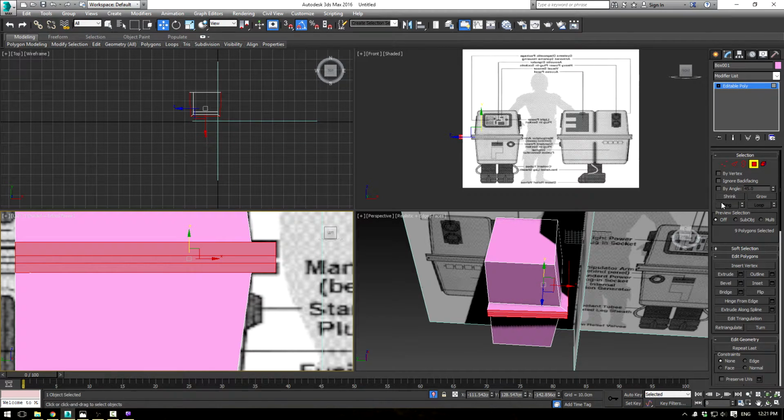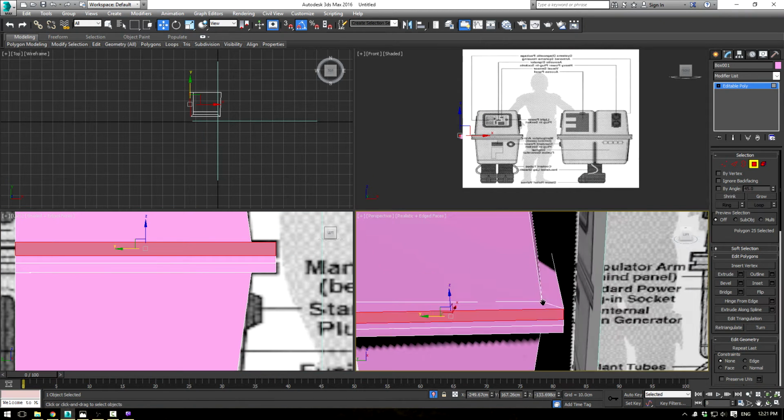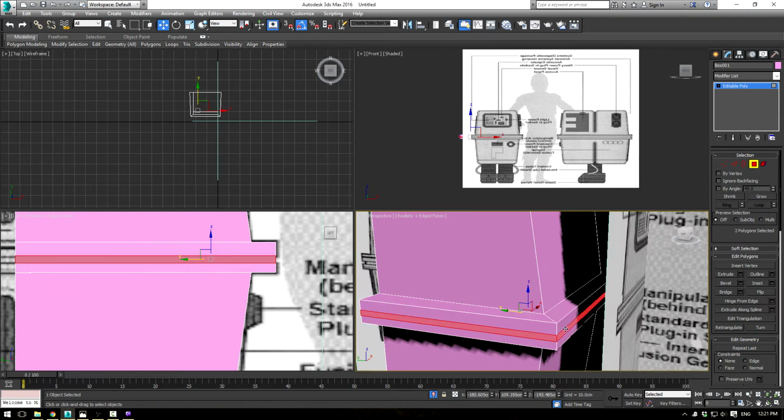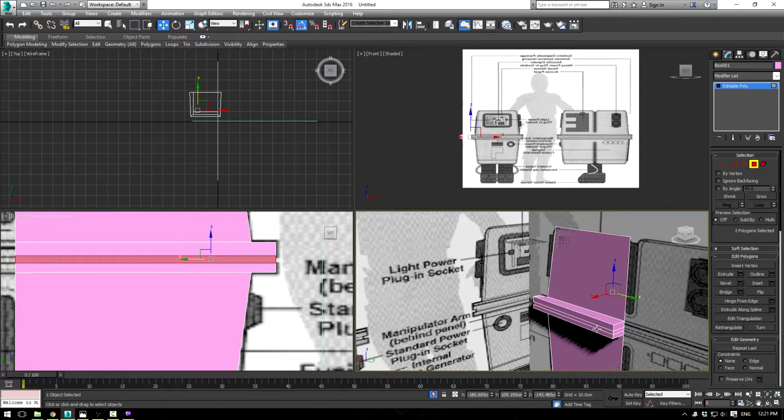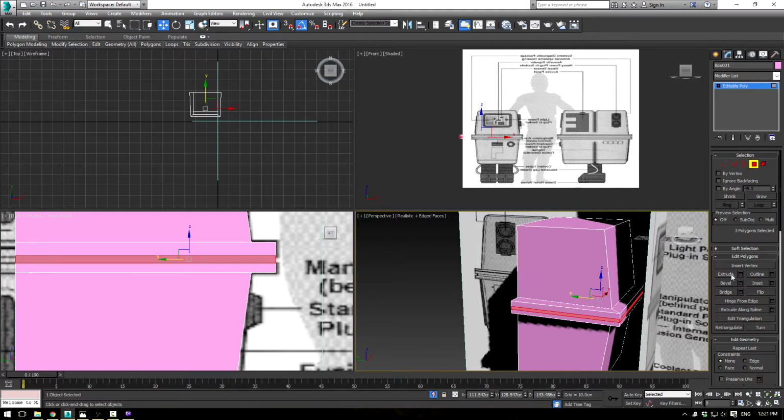Now if we shrink that, with luck, we'll be able to just click the internal polygons here. Alright, and let's extrude. Again, we're on the local normal, but this time we're going to extrude inward. Okay, just so we get that perfect little bevel right there.